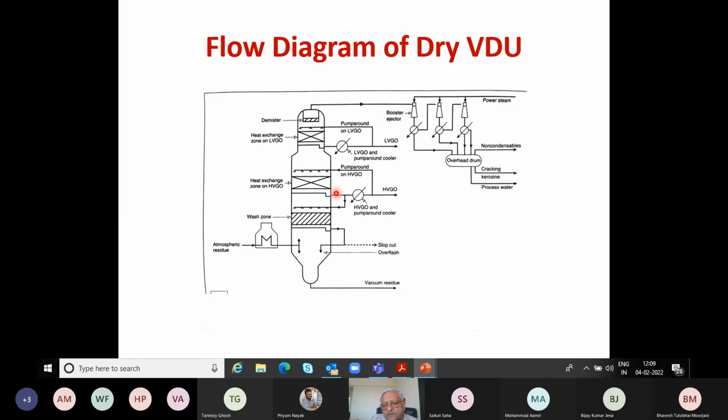So this liquid, when it gets withdrawn from the column, there's a pump, and the discharge from the pump goes into three different directions. One part goes as a reflux to the column itself. So the vapors, when they come up, get washed by this liquid.